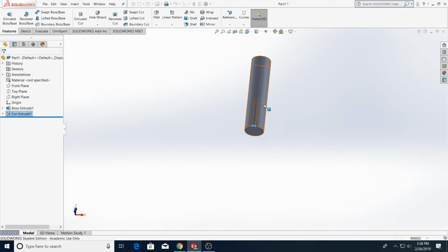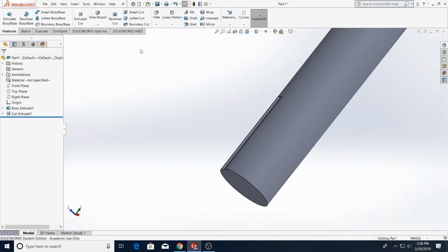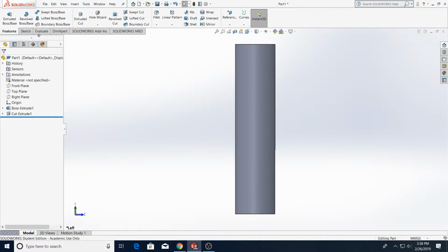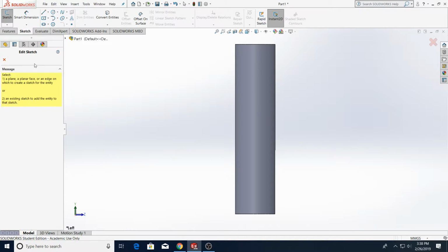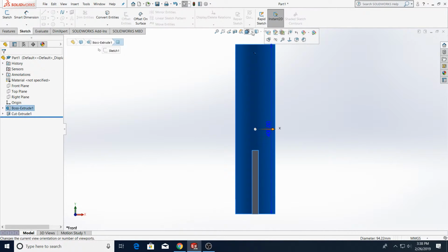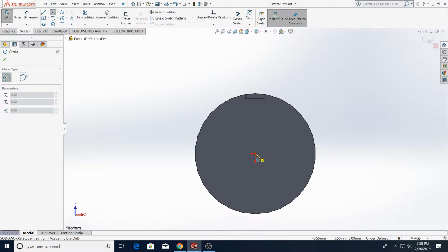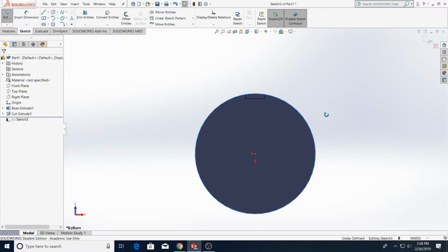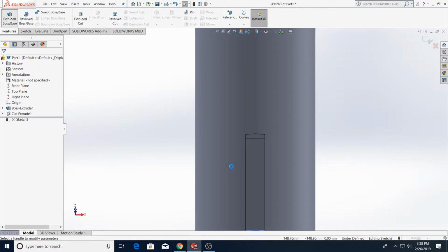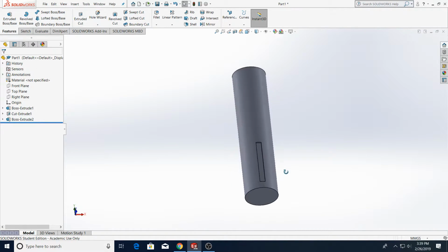So if you were to approach it like this, you would either have to go back in and create another extrusion to fill in the bottom part, which you could do from the side. Like, for example, we could draw on the bottom again. Let's go with this perspective here. We draw another sketch on the bottom, and then extrude up a certain amount, we could fill in what we wanted to fill and leave only the cutout in the bottom section. That's probably the most simple way to frame that logic in your head.